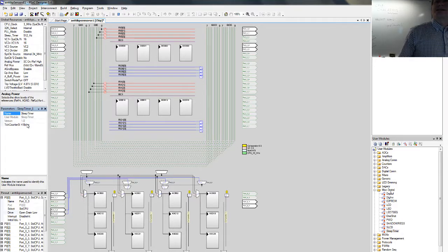So basically this is the divider size, and I don't see any reason to use any less than 4 bytes. It doesn't make the code any longer practically if you use that 4-byte divider, since basically this divider is a software divider. So what is the biggest count you can put there on the sleep timer?